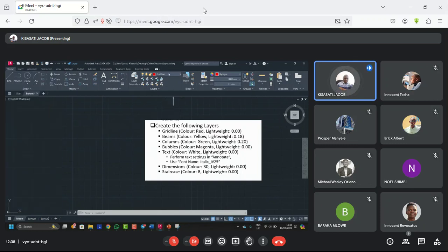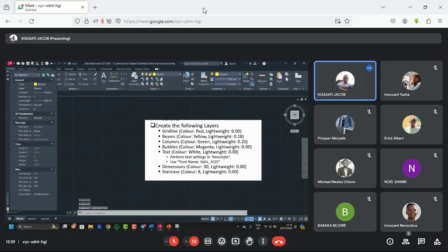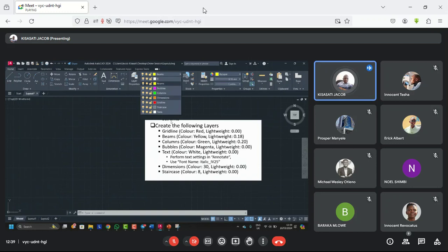After that, we'll turn on beams. We'll make this one our default layer. We'll go back to these properties, but I dislike using this. So what you can do after making this layer as current layer, you just press Control 1. So Control 1 and the property of that will come. So make this one to be the line weight for the beams. You can make it 18, as you can see. So 0.018 like that. Then close this window